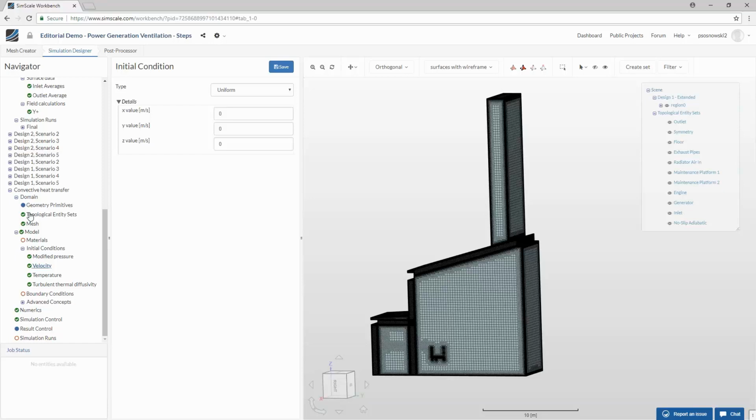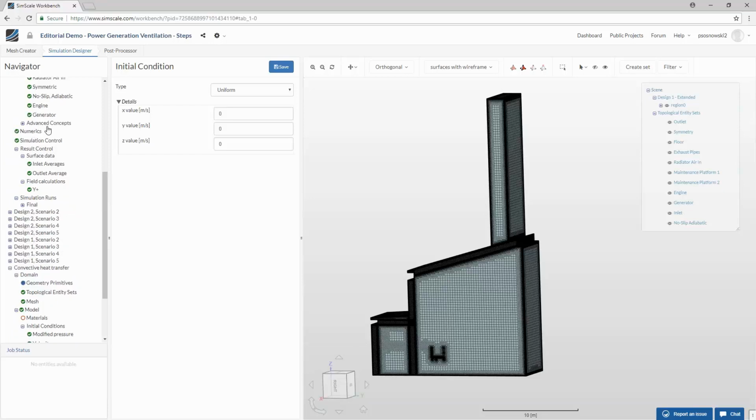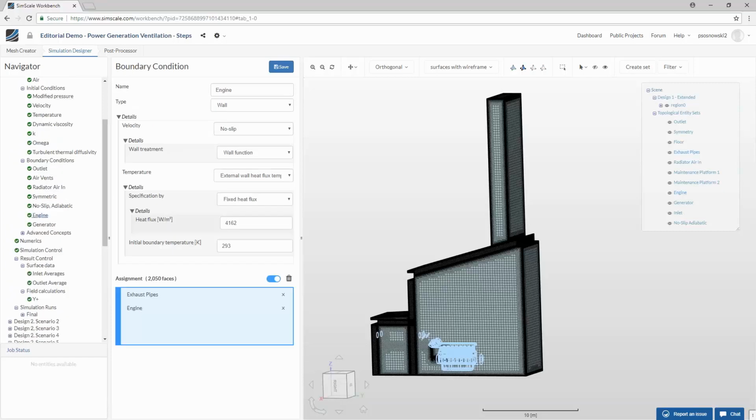Okay, so with y plus, you try to ensure that your flow is actually properly resolved next to the wall, and the values are 30 to 200 if you use wall functions. This is done, let's say here. Once we select one of the boundary conditions, you have the wall function set up for the behavior of velocity.